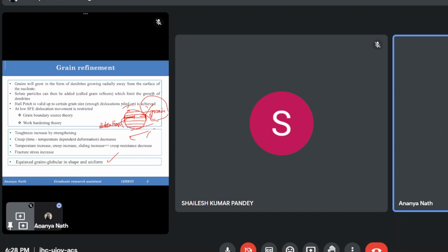homogeneous and heterogeneous nucleation. So this was, up to this point, it's like we are having one grain or one microstructure. This microstructure is having this grains with differently oriented lattice structures, and out of this particular microstructure we are just deforming the thing, or just applying some external load, due to which we are just refining the grains. Means out of this old grain we are now making small grains out of it. So this is grain refinement.